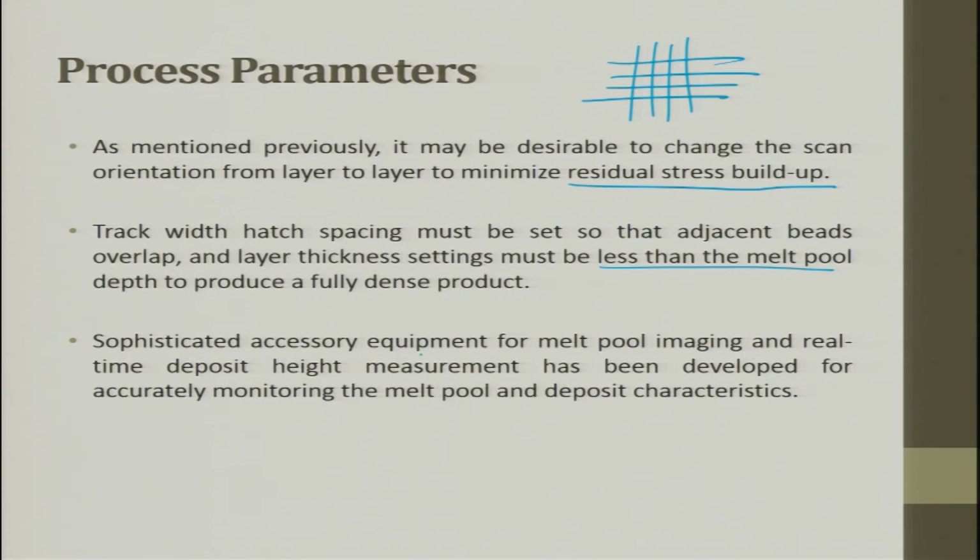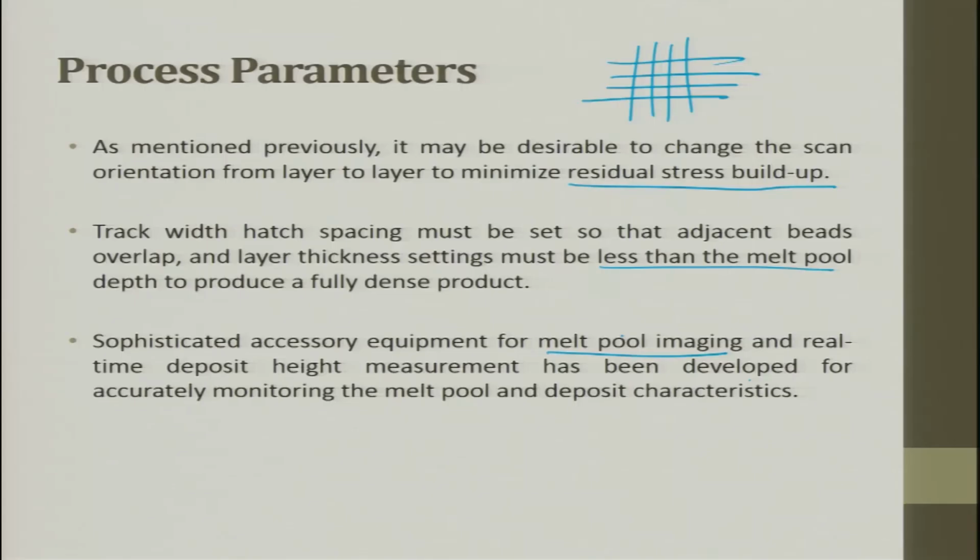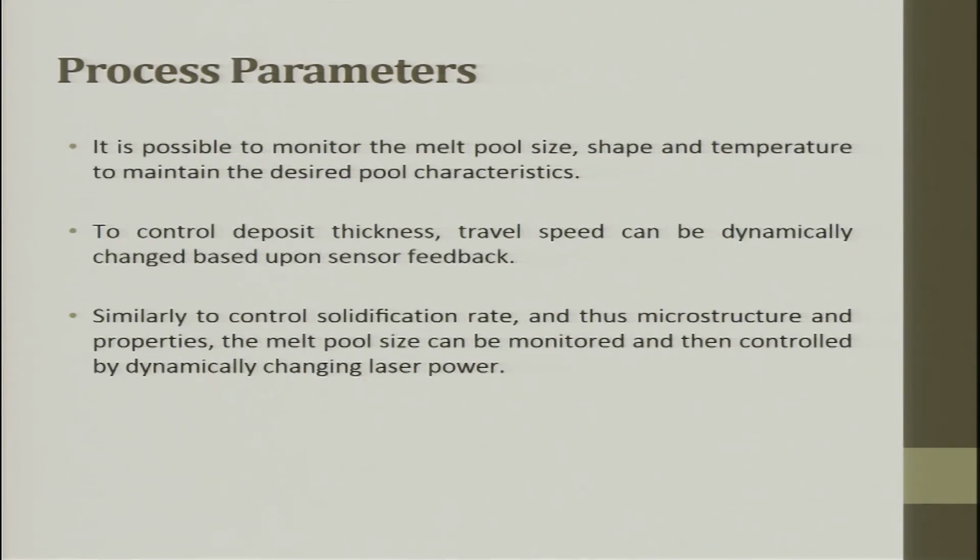Sophisticated accessories and equipment for melt pool imaging and real-time deposition height measurement have been developed. What is the temperature at the melt pool? Because if there is a larger melt pool, this is going to create more melting and solidification, and we have to balance it. The other thing is, when the melt solidifies, it does not give you uniform height or thickness. So, we need to measure the melt pool temperature using imaging techniques and measure the real-time height, so that we know what powder flow to give.